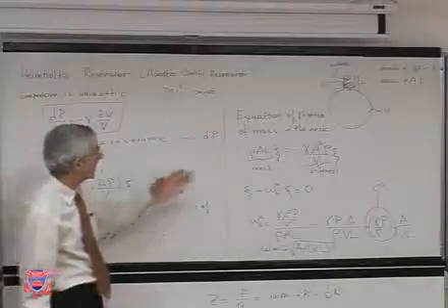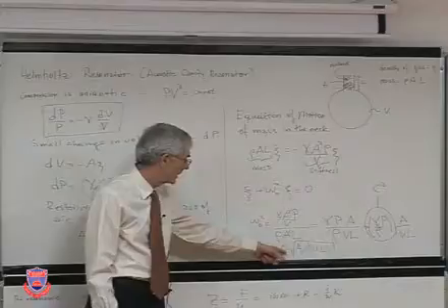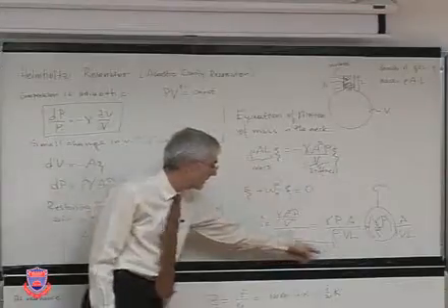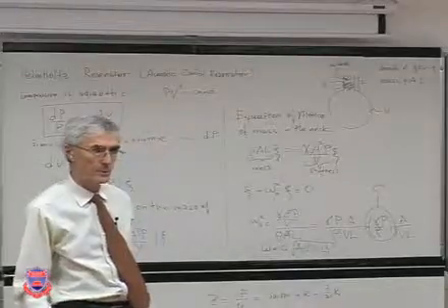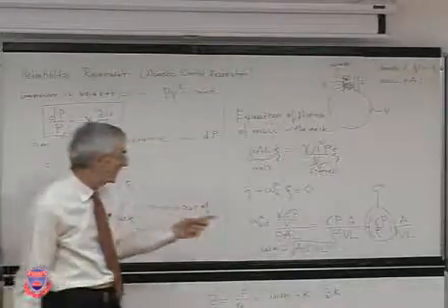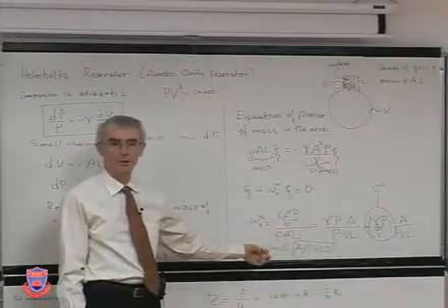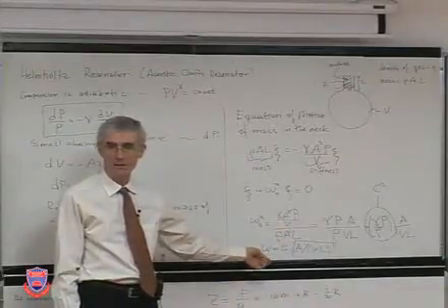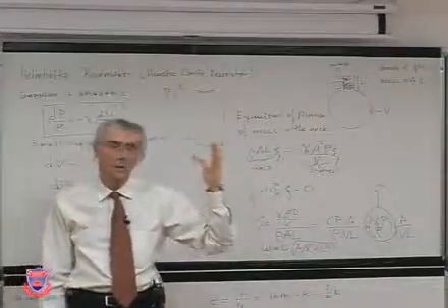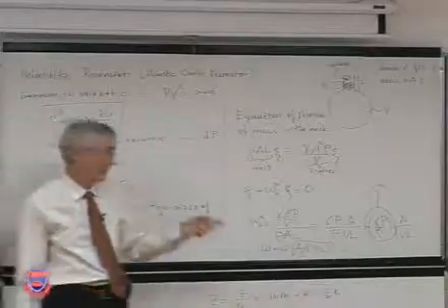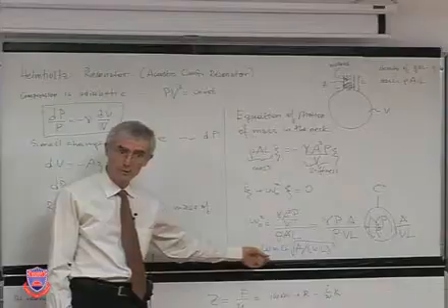Okay? So in this system, the cavity resonant frequency is determined by the speed of sound and essentially the geometry of the system. Okay? So if you have a different gas, helium, for example, you're going to have a very different resonant frequency. Or if you're at very high altitudes, temperature is different, speed of sound will be somewhat different, so you have a different natural frequency.